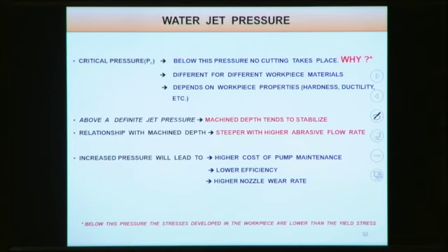Increased pressure leads to lower efficiency, because with increasing pressure your velocity increases, and with this high velocity the abrasive particles coming out of the nozzle wear out the inner surface of the nozzle, so you have to change the nozzle. So increased pressure will lead to lower efficiency, higher nozzle wear rate, and also higher cost of pump maintenance. If you increase the pressure, pump maintenance will be more.